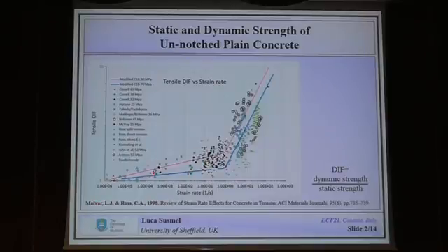You can basically see two regimes, that is, as the strain rate increases, of course, this ratio increases, and when the local strain rate approaches about 1 strain per second, there is a quite evident change in the slope of the curve. But no matter what you do, in the end, in this schematization, so if you consider strength and local strain rate, the relationship between these two quantities can be expressed using a power law. And if you go through the literature, you can find a lot of nice models, very sophisticated, but in the end, from a mathematical point of view, what you really need is a power law.